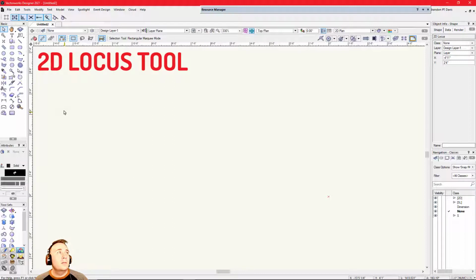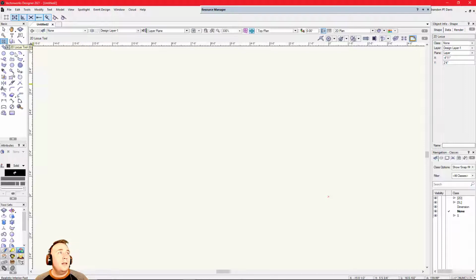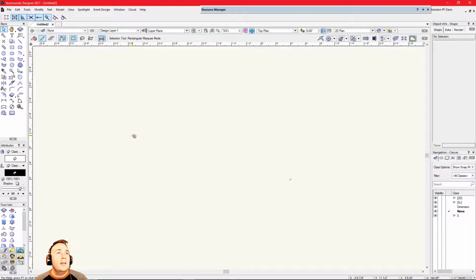The 2D Locus tool, which is the icon that looks like the letter X, is located here. A 2D locus is simply a reference point that can be used in Vectorworks when drawing. This document contains a red 2D locus at 0, 0, as this reference is very common when working in theatrical practice. The benefit of a 2D locus is it allows you to have a point that's viewable on the screen, but not printable on the page. The hotkey for the 2D locus is the letter 0.